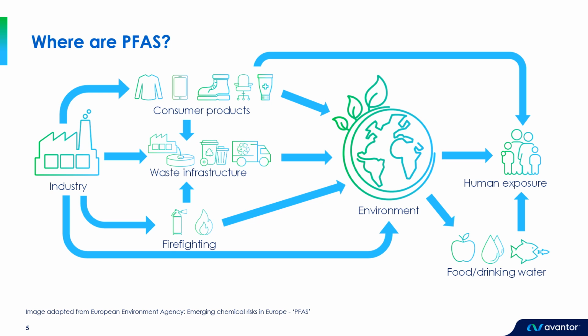So the waste infrastructure section has received a lot of attention. Wastewater treatment plant processes may not fully remove PFAS before discharging treated water. And additionally, leachate from landfill can be another important source. It's also worth considering that the stability of PFAS compounds means that they can outlive other materials that are used within products that enter the waste infrastructure. And so as those materials, products degrade over time, you have the potential for the release of legacy PFAS